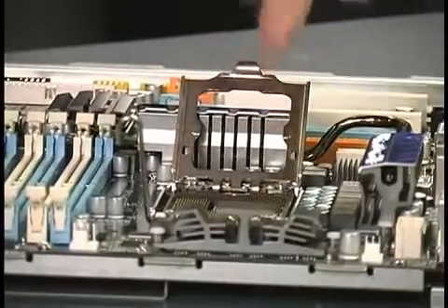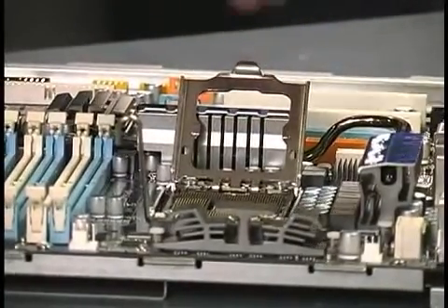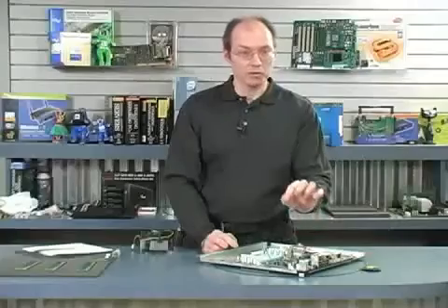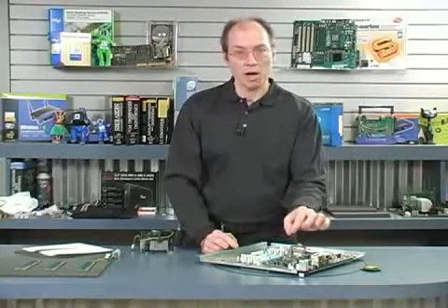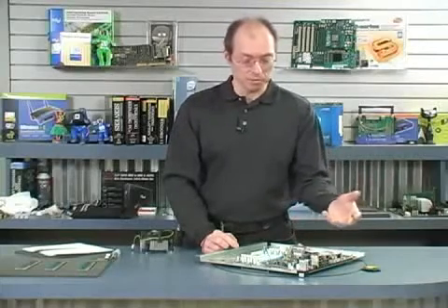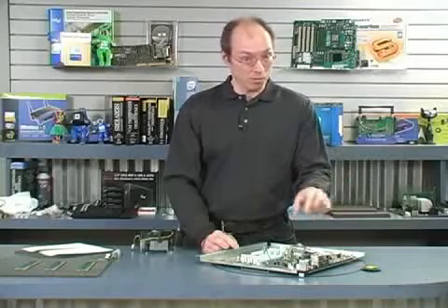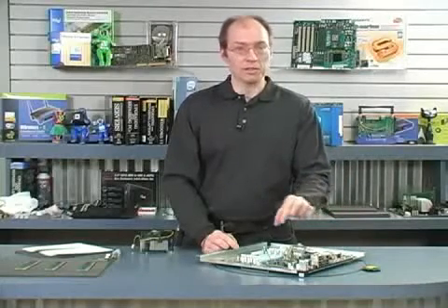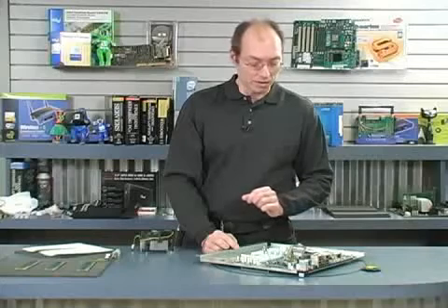There are, as I said before, 1,366 very fine, tiny pins in the socket, and you do not want to touch them. Just the slightest touch, snagging it with a little bit of cloth, something like that, will bend those pins and basically render the motherboard destroyed. And when you go to turn it in for a warranty repair, they will look at that, and if they see that the pins were bent, you may have a problem collecting on that warranty.